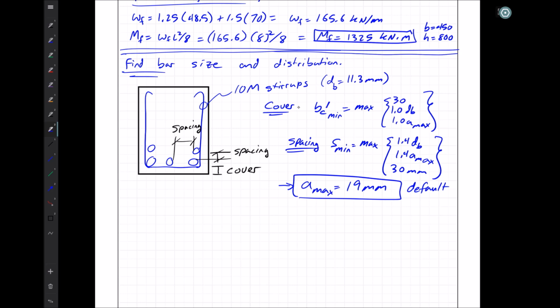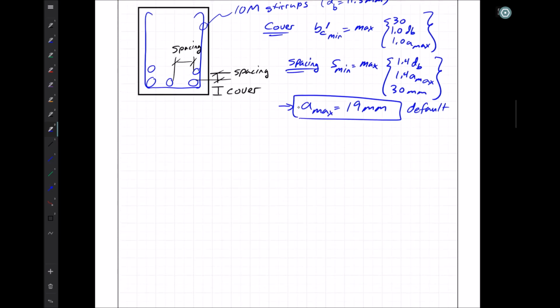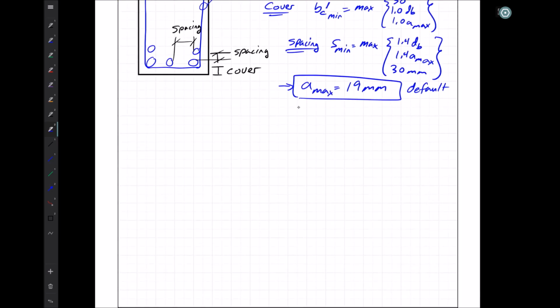Now, this is usually for very high strength concretes, but in that case we're going to remove a lot of our large aggregates and use smaller size fine aggregates instead. So there's a whole host of reasons why we'd have different A values, but typically for most concretes in the range of 30 to 55 or so MPa, our largest concrete aggregate size is 19 millimeters, which is 3/4 of an inch.